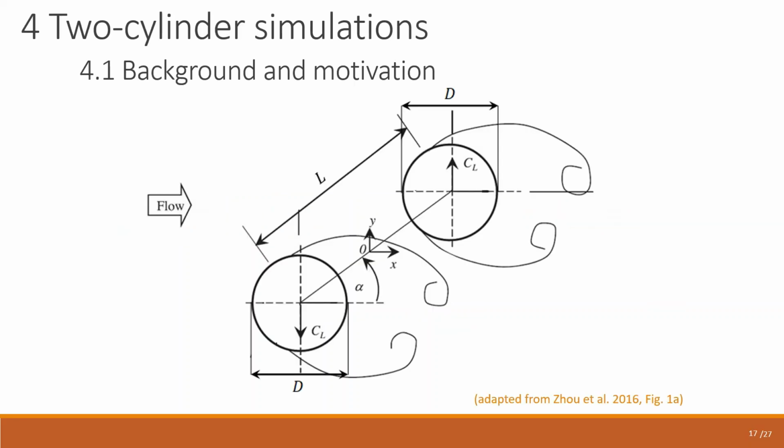To further develop the simulation and increase the accuracy of the solution, a multi-body simulation is developed. This simulation has 2 cylinders, one representing the hydrophone and the other representing the mooring line. We investigate whether there could be a combined effect when the wake of one cylinder amplifies the wake of another cylinder. This could cause a larger frequency which could get closer to the acoustic frequency of rainfall and interfere with the acoustic measurements. This could reveal if the mooring setup needs to be redesigned to prevent acoustic interference.